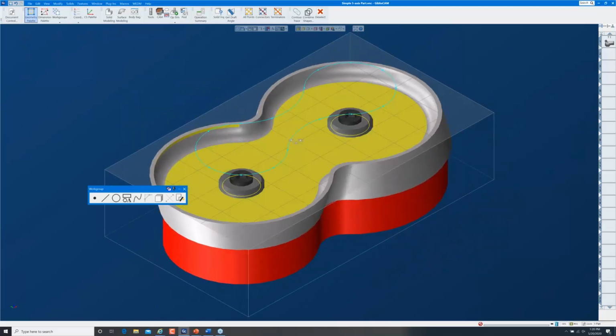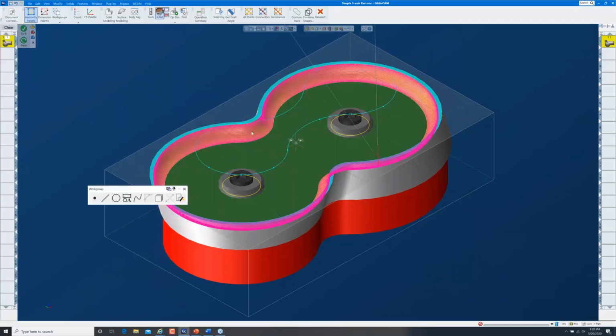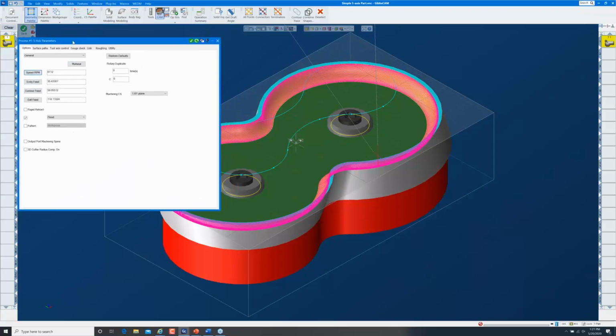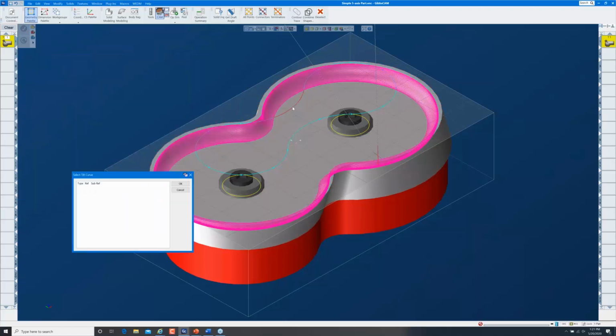So with that built, I'm going to load my process back in, which reselects everything, by the way, rebuilds my toolpath and reloads my process with all the parameters set the way that they were when that process was built. So all I need to do to tweak this toolpath is come over to my tool axis control and come down and say, I want my tool to be tilted through a curve. And my tilt curve is going to be that.